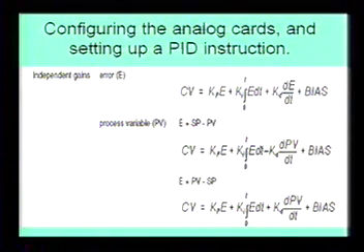Because if you've got too big of a pump and you turn that pump on and you crack that valve open and all the water comes rushing out of there much faster than you can put the water into the tank, you're never going to control it, right? You're going to slam that control valve shut and deadhead that pump and destroy the centrifugal pump. So then you would actually have to have a loop around the pump, which is not a bad idea anyway, just to keep it from deadheading, but that's a whole other story.